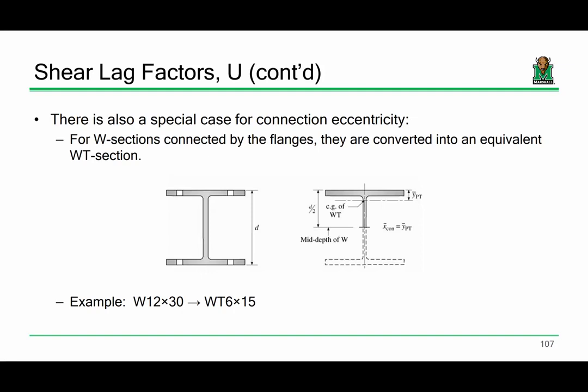If you use the Y P right now, bad. Don't use the Y P. The Y P quantity is related to bending. Specifically, it's the location of what's called the plastic neutral axis. You don't understand what that means yet? You will. We'll talk about bending and plastic neutral axes probably in the March-April timeframe. But for now, I want you to be crystal clear: avoid those for now. You'll understand what they mean later, but just don't worry about them now. Everybody okay? So that's X bar in a nutshell. What about the connection length? What about L sub CON?